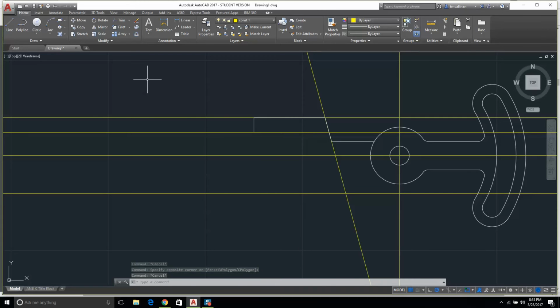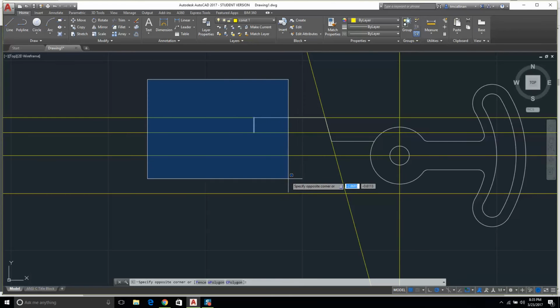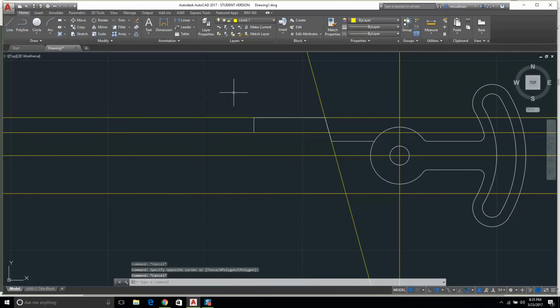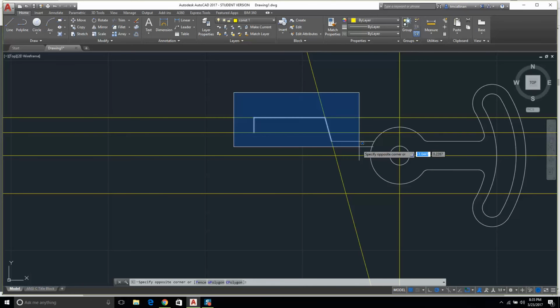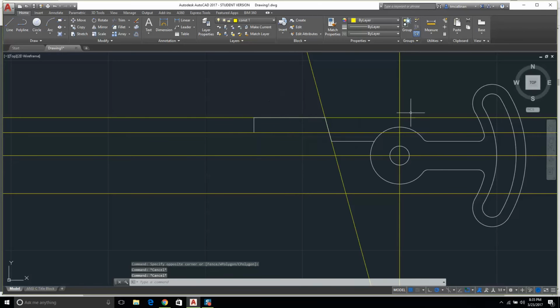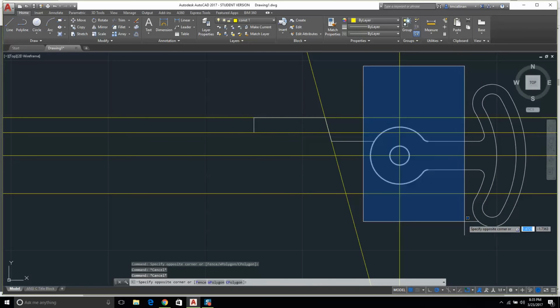If I click here and I go all the way to the right and I click here, what is selected? Whatever is fully enclosed in the rectangle, it's going to be one single line. If I click here, it kind of tells you already, which is nice. If I let go, how many lines are selected? It's showing you already. That's a nice little trick. 3 lines. So whatever is entirely enclosed within it, it will select.